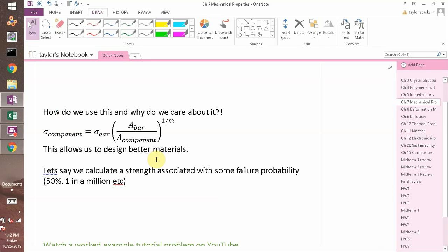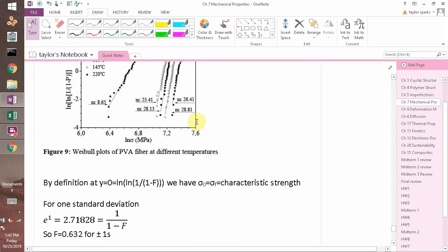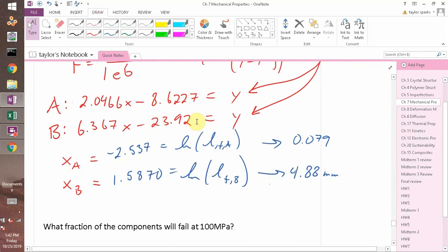So let's go back to our example. We did our rubber band, and we know the elongation, right? Let's do sample B. We know the elongation at which we get 1 in 1 million to fail. So now let's say that we've got a great big sample, that the area is, I don't know, 100 times more. How many will fail if we did that exact same thing? Or in other words, let's first take that exact same elongation and the failure rate that it was at. If you did a giant fan belt, what would its elongation be to have the same failure rate?